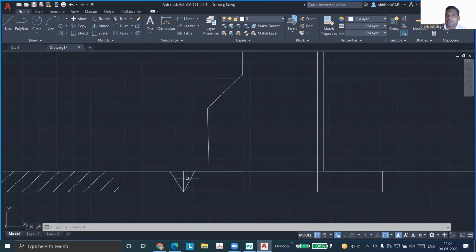These are not standard nozzles. You have to design it first, and provide the reinforcement, because these are integrally reinforced nozzles. You have to build that into the forging, machine it accordingly, then order it. They will supply the forging, then you have to machine it to the shape you want. That is the step, so it takes a really long time.